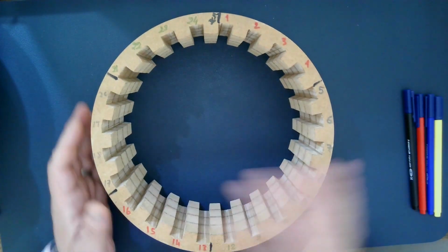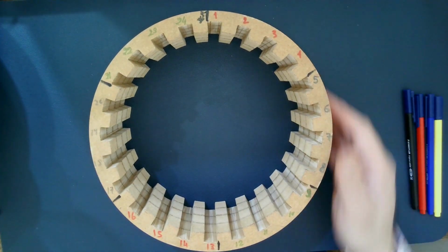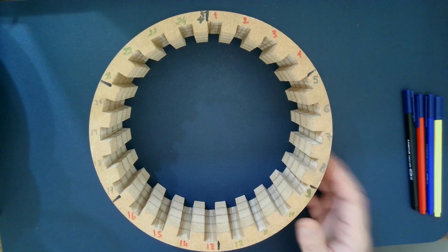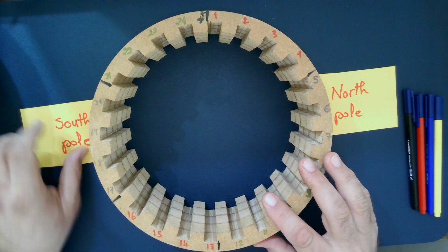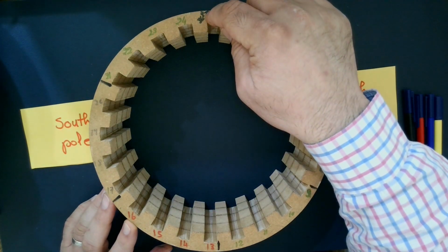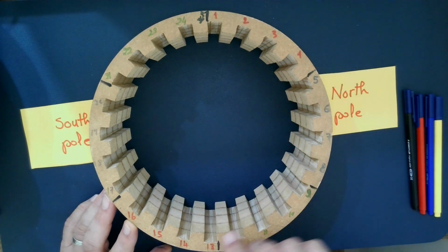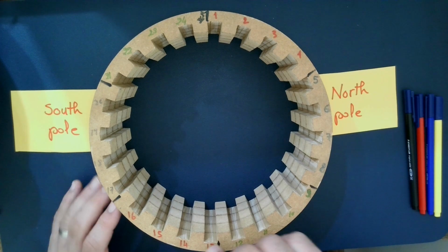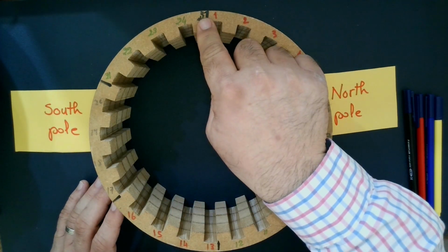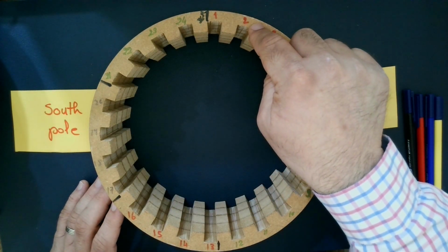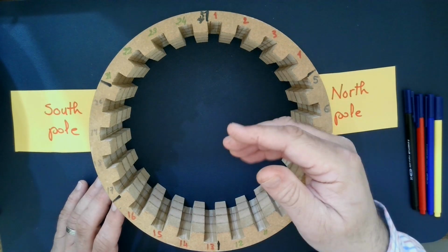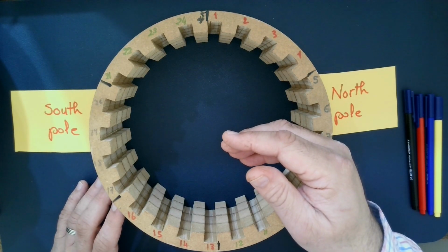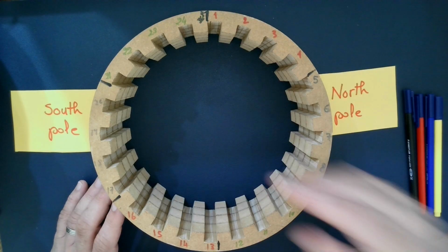That one is the stator length L, and we have here 24 slots. We have North Pole and we have South Pole. So if we say that one is the North Pole in this sign, that one is the South Pole. So per pole we have 12 slots for the North Pole and we have another 12 slots for the South Pole. So the number of slots per pole is 12. So how are we going to start winding this machine or this stator using the 3 phases?